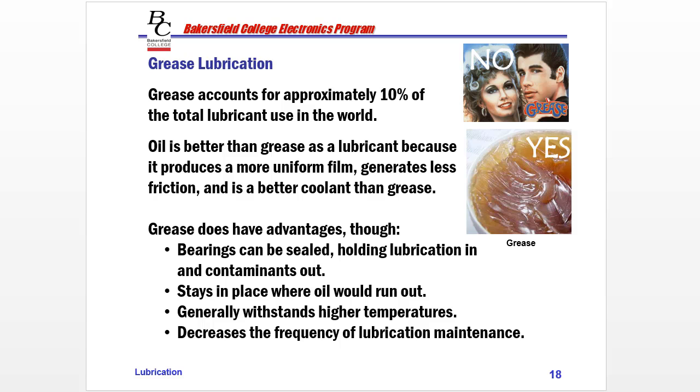Those tapered roller bearings, we'll be talking about those next week, by the way, are actually filled or packed with a grease. Now, that will last much, much longer than the oil in our engine or the transmission fluid in our transmission. So it decreases the frequency of the maintenance.